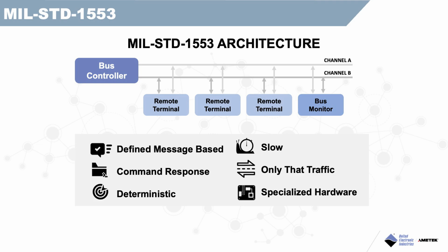So if we look at MIL-STD-1553 specifically, it is used in military systems. It's pretty old, but also very robust. How old? Well, 1973 old. It is redundant and deterministic. However, it is slow. It does require specialized ASICs to operate and can get expensive.